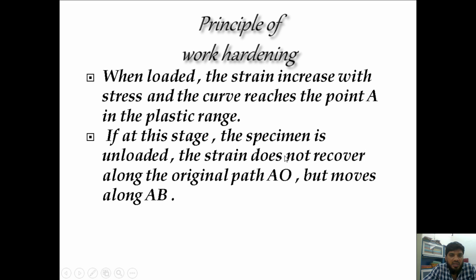Next, a comparison of paths ACD and AD dash shows that cold working, that is, plastic deformation, has increased its yield strength. Yield strength is the point where the material changes its nature from elastic to plastic, and ultimate strength is the maximum strength which a material can withstand. After the ultimate strength, the material will start breaking. That strength is called the ultimate maximum.